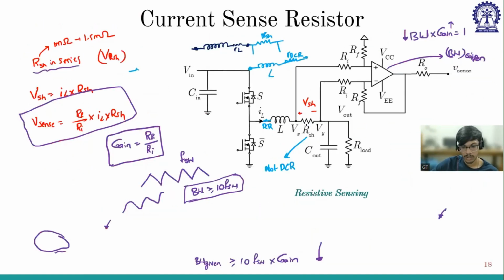Sir, the other doubt is, in the next case, we said the gain bandwidth should be unity. Suppose we consider a low pass filter magnitude plot. When we increase the gain, the bandwidth also will increase, sir. No. See, what gain bandwidth means is that every op-amp has a gain, right? Now, if you increase the gain, the effective bandwidth of the op-amp will be reduced.